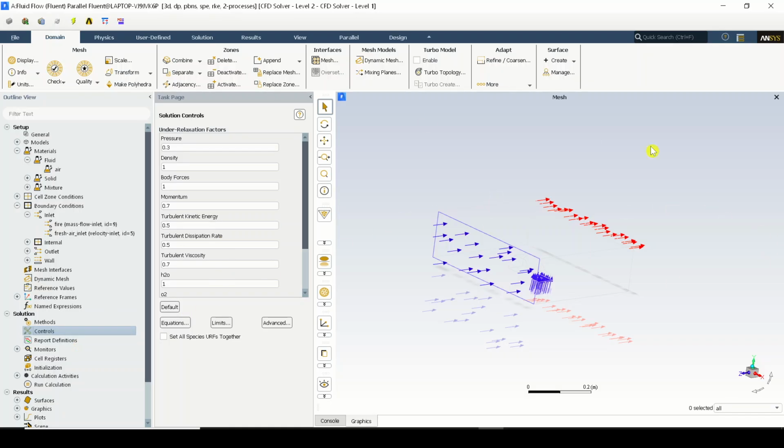Generally this kind of flows that we have, the kind of flows of multi-species which have low velocity values at inlets, represent a kind of transient behavior. So the residuals you will be getting in the flow will often be oscillating, and in that case you cannot totally rely on the residuals for concluding the convergence. Clear?